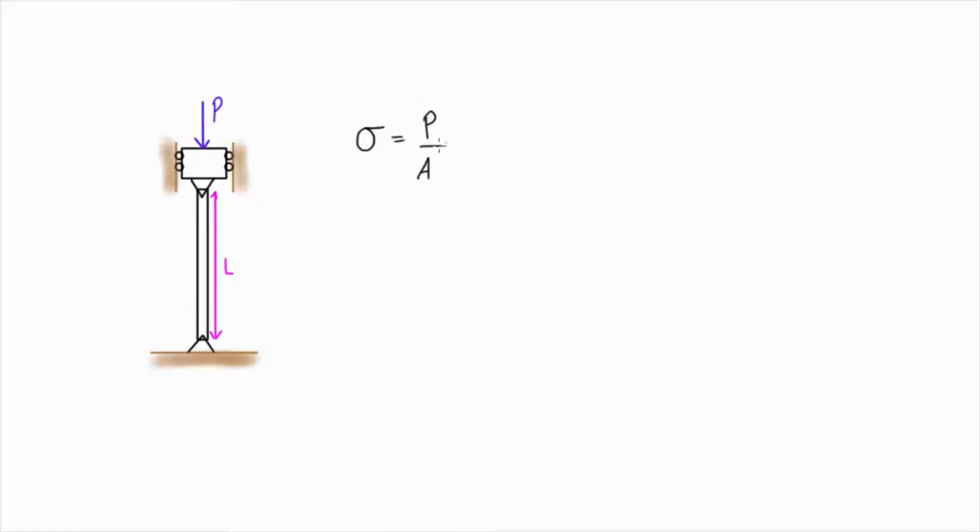That's because if you slowly increase that applied load in tension to the point where you get the material yielding, we're going to find out what that yield stress is. And from yield stress, you apply your factor of safety, and then you're given your allowable stress, which is basically the maximum stress that we're going to let the member be subjected to, and we're not going to be concerned about it yielding at all.